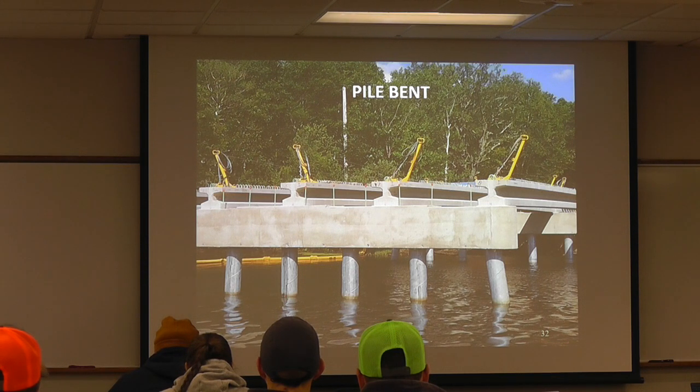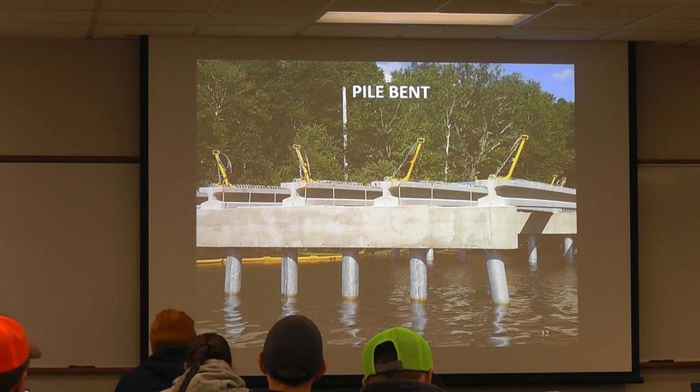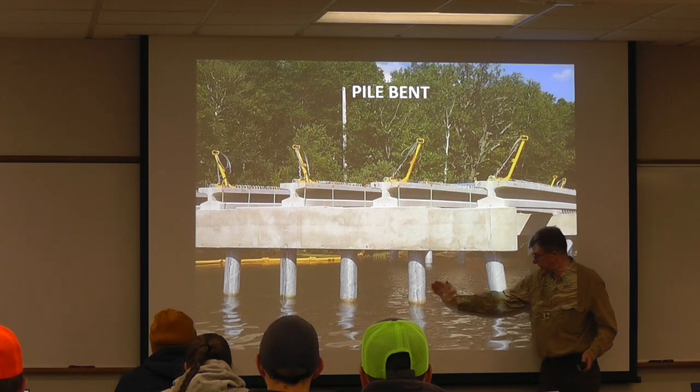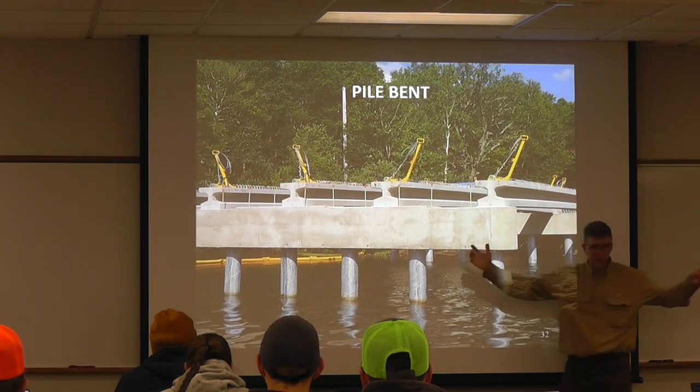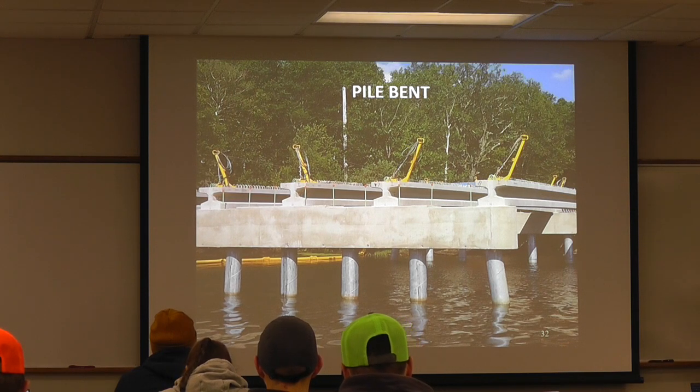It's not a full pier wall. You're not designing it for loads. You're more designing it to be something that will restrict the timbers and the logs that are floating down from wedging themselves in. To deflect logs, yeah. So instead of a log coming down here and all of a sudden it twists itself up and gets behind there, and pretty soon you have a big old mess, it'll deflect the logs.